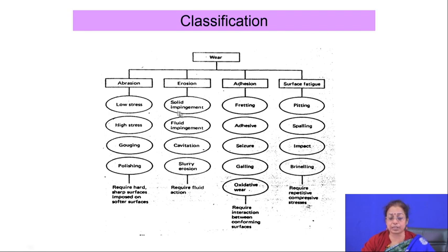Another important feature about all these things which I need to mention is that, apart from the characteristics, you will find that in 75% of the cases wear proceeds by the loss of material. So, when there is wear phenomena, usually there is loss of material from the surface. It is progressive in nature. So, it is not really very fast as is fatigue or as is compressive failure of the component, but it is progressive in nature.